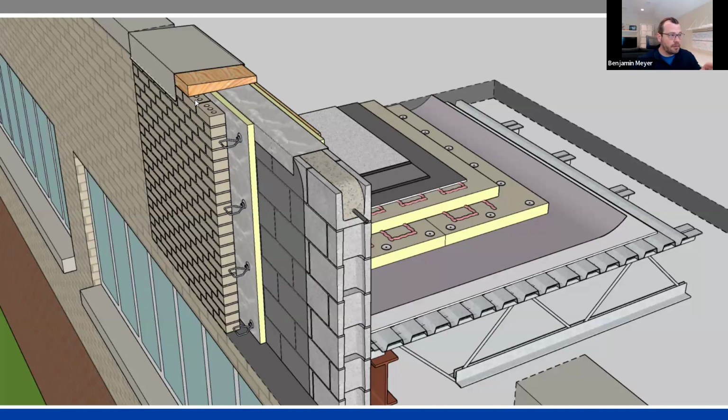But one thing you'll notice is the first thing put on this wall likely is this piece of flashing below the parapet blocking, and that's going to do a lot of things for you. It's going to protect the wall from filling with water while we wait around for the air barrier to be put on the outside, for the roof to show up, for the coping to be put on. One of the worst things I've experienced is when you have these open cores of CMU for months, or just the wrong week when it rains. It can take a long time for that water to dry out of the system so that you get a dry substrate, because you have columns of water essentially inside your wall.